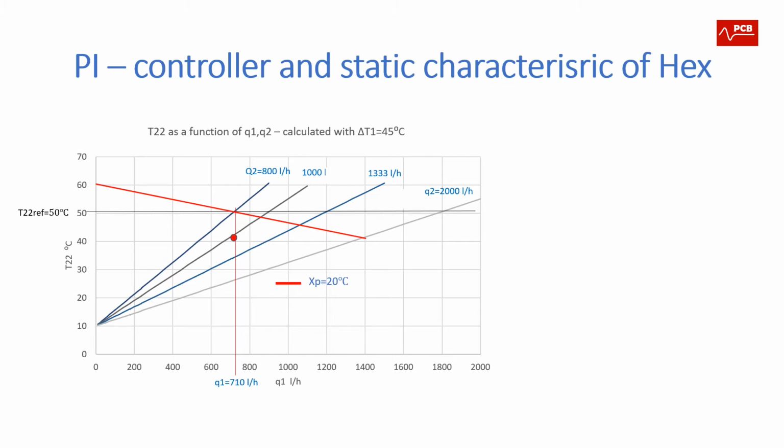The P component reduces the error, but there is still an error present, which is eliminated by the integral part, which is integrating based on this error input, and eliminates the error completely. And further, if there is a further increase of consumption, it is the same story. First the proportional component reacts and the integral part eliminates the error completely.